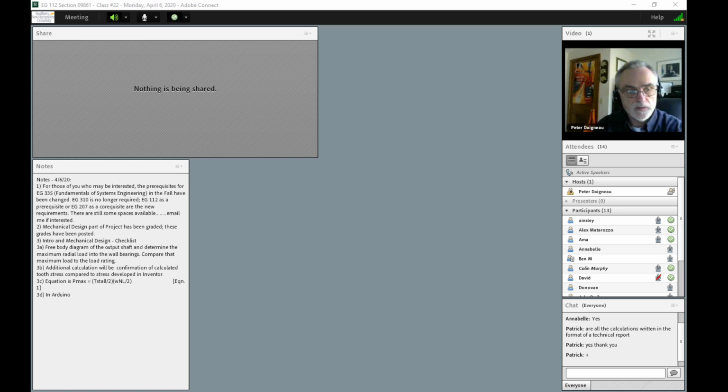At the top of your code, above your setup section, you will want to use the hashtag include function, and then specify the particular library that you need to have access to as part of your code. You will need access to the LCD display library.